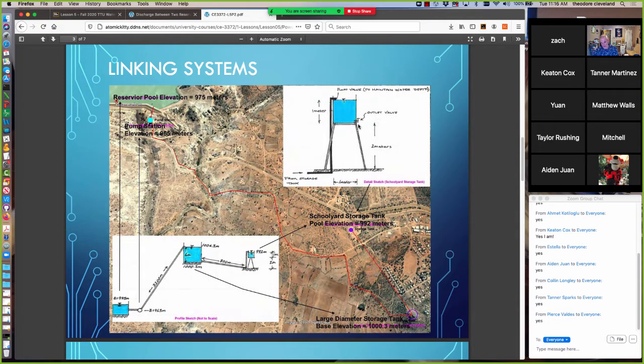A second thing that can conceivably go wrong is this output valve can fail in the open position. Someone can draw water from it. I have this thing 6 feet in the air, more likely to be down where you can get to it, where the children can get to it. But they could leave the valve open, or the automatic spring closure on the valve could fail, and that could fail in the open position. And the question there is, again, what's the flow rate coming out of the system? How much water are we going to lose over time? And in that case, more importantly, can the pump provide enough makeup water to keep the system full of water until we get around and fix the broken valve?